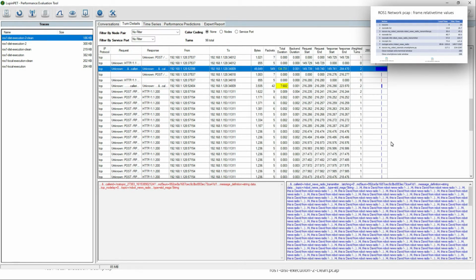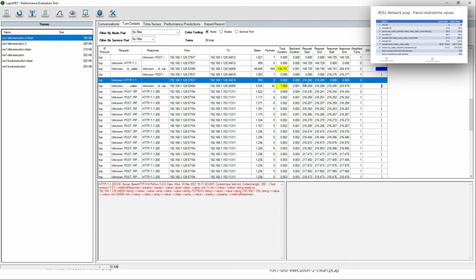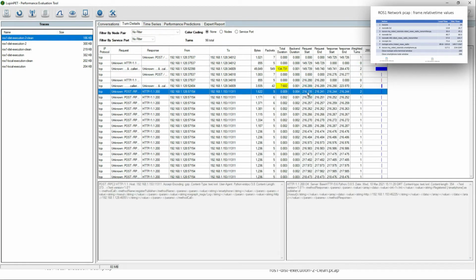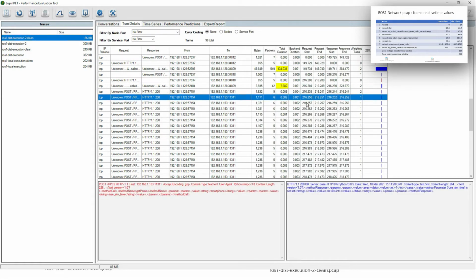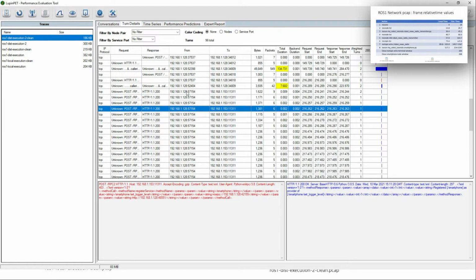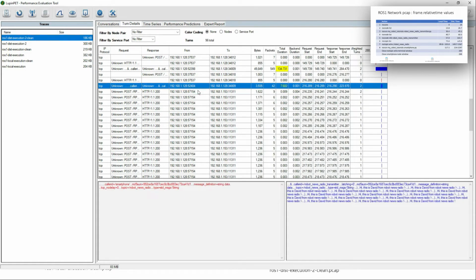Now let's have a look at the ROS topic smartphone subscriber running. So that starts at 214. So it looks like it's 216 on here. It's showing the time, and it's going through registering the subscription as you'd expect. And then when the actual subscription is active, we can see the publisher, which is running on 128. And I think this port, 52404, represents the node, and it's talking to this port on 128.